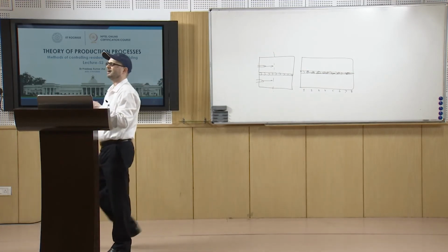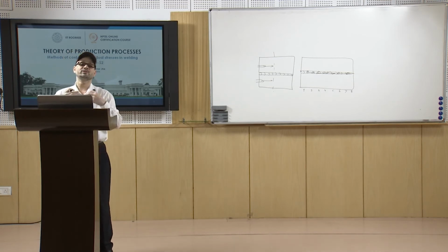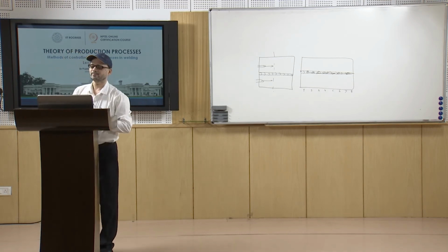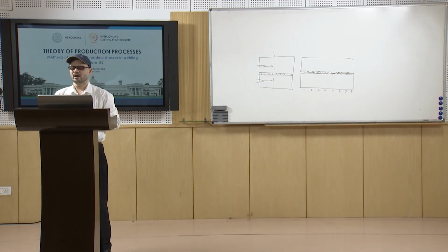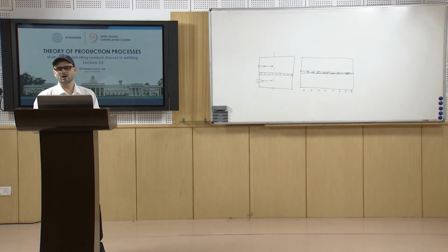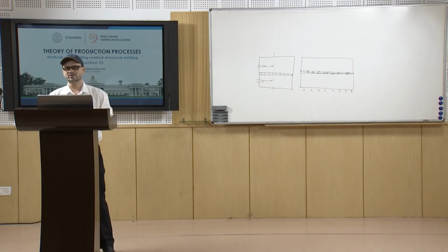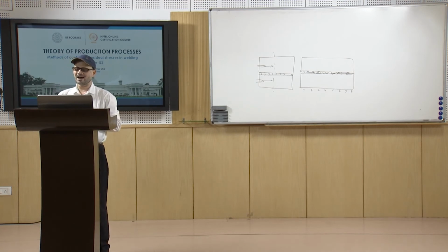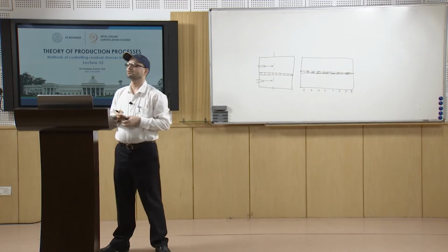Depending upon the type of component or shape of the component, we do the welding, and here the important principle which is applied is that we want to assure unrestrained transverse shrinkage or large straining length for butt welds.